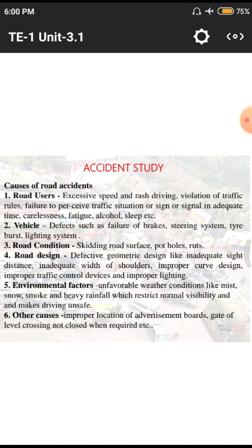Next one we have is potholes. That means due to poor construction designs of the roads, in rainy seasons we observe these potholes. That means in a few places there is no proper densification of the roads by rollers. Automatically, those things lead to pothole formation in the rainy season. We need to arrest that pothole formation. Why? Because if there is a pothole, automatically the speed of the vehicles may decrease and there may be a chance of accidents. That is a major condition for the roads.